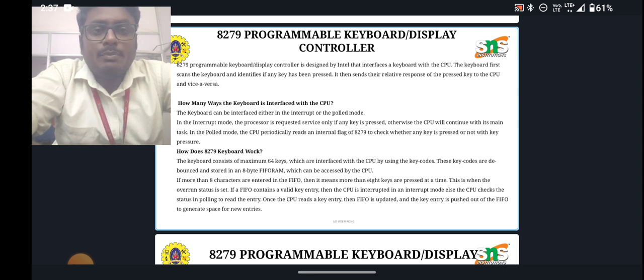How does the 8279 keyboard work? The keyboard consists of a maximum of 64 keys which are interfaced with the CPU by using key codes. These key codes are debounced and stored in an 8-byte FIFO RAM which can be accessed by the CPU. If more than 8 characters are entered in the FIFO, it means more than 8 keys are pressed at a time. This is when the overrun status is set.